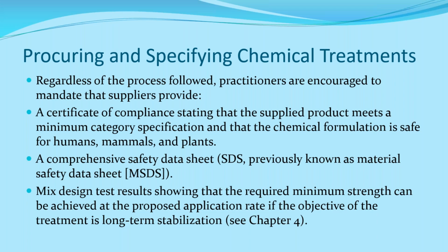I've seen a number of agencies do what's called an otter seal, or I call it a BST, which is a double seal, and it's pretty much a seal coat, and then you seal coat over the top of it, trying to develop a little bit of structure and armor that surface of that roadway.